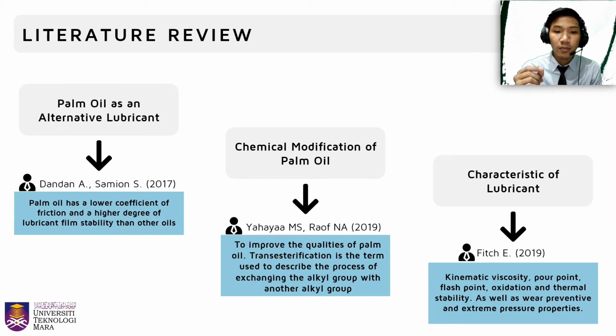Next, the extreme pressure qualities are required for use in certain applications that may encounter significant loading or shock in lubrication. By Noria Corporation in 2019, anti-wear qualities are required to prevent machine components from wear and metal loss under boundary lubrication conditions. They are activated when they come into contact with heat, forming a coating that reduces wear.